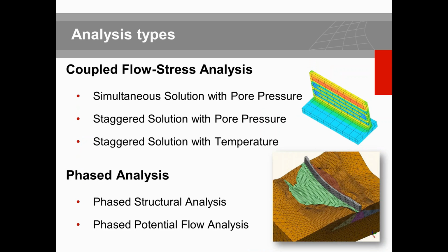After performing the potential flow analysis, you can combine and find its impact and effect on the superstructure. So if you have some sort of groundwater flow analysis and the development of pore pressure, you want to see how this affects the failure of the superstructure. We have either a staggered analysis, which means first you perform potential flow and then nonlinear structure, or you can have a coupled approach. In that case, the program solves PU or TU for you.